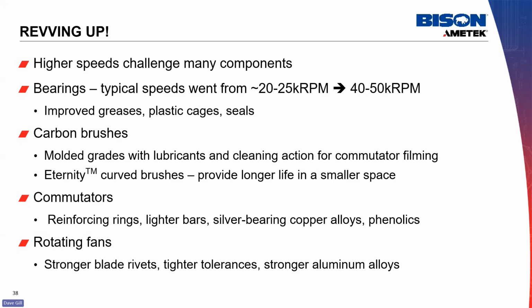Bison also developed and patented the curved Eternity brush used in several of our product lines, enabling a longer carbon to be fit into a smaller diameter housing and producing life of 1,200 to 3,000 hours, depending on the power level.